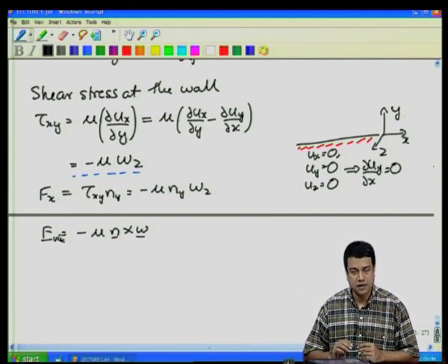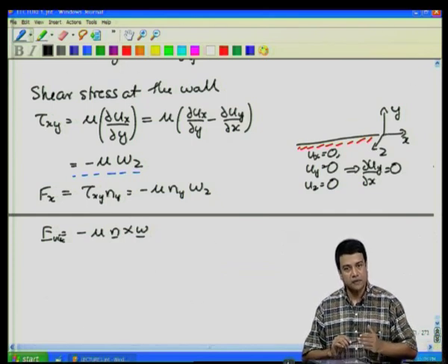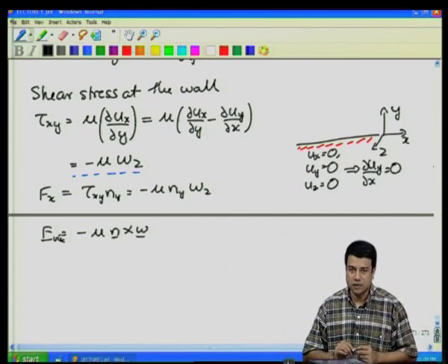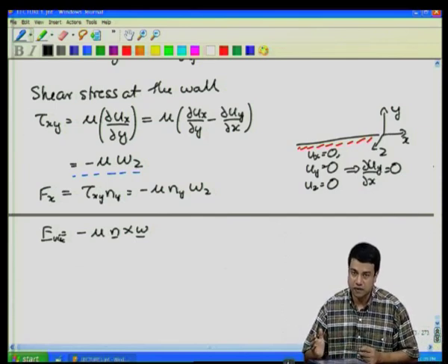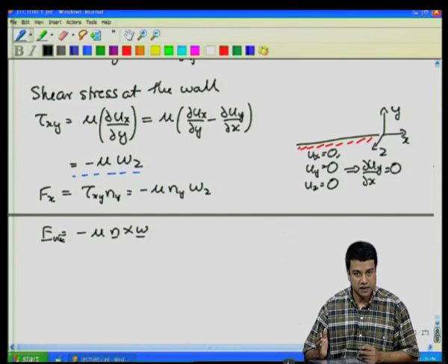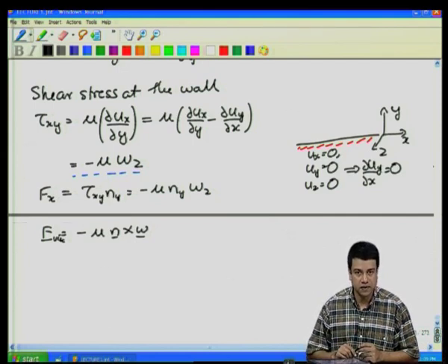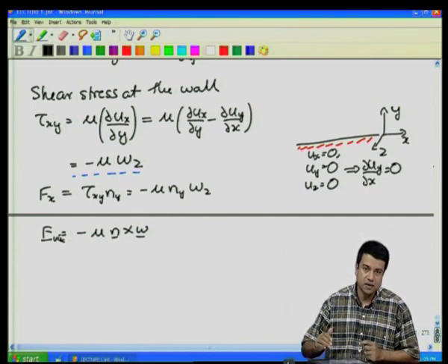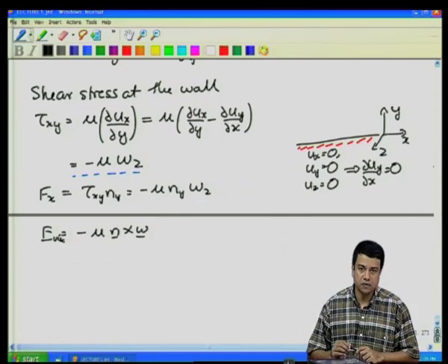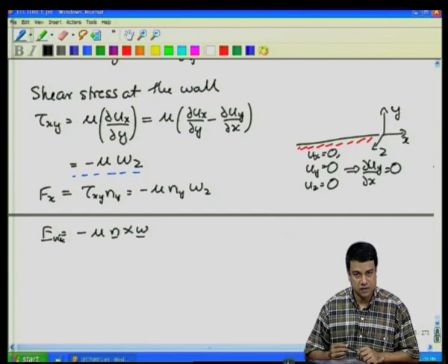Similarly, in this case, the vorticity has a specific value at the surface, and of course, it varies as you go into the flow depending upon the convective, the viscous, and we have this additional vorticity intensification term. So, in accordance with these three terms, the vorticity would vary as you go within the fluid. However, in order to find out how much vorticity there is in the flow, it is not sufficient to know what the vorticity at the surface is.